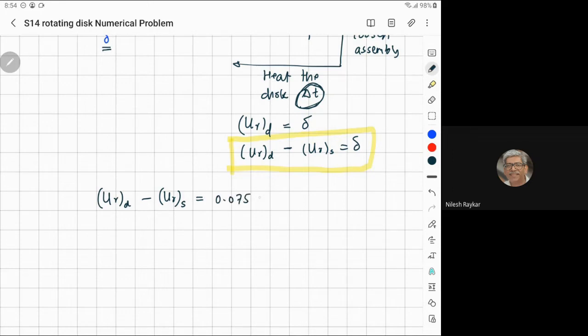So I will do all these calculations in meter units because we are having the density. In this case, the forces are being calculated based on rho omega square. So if you consider millimeters, then the density also needs to be converted, and there will be some unit-wise mismatch or error could happen if you are not careful enough.